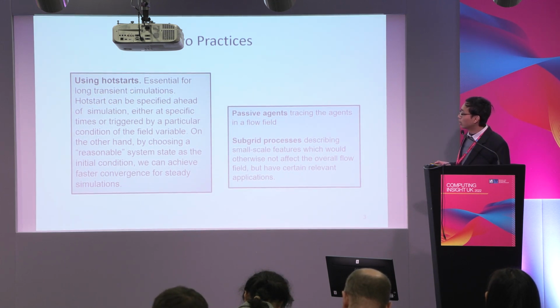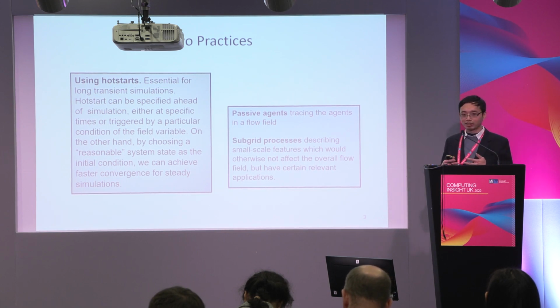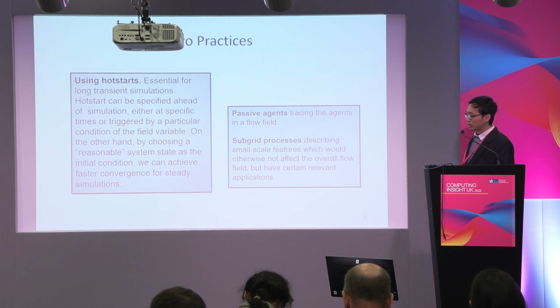It's also for using hot starts. For example, we have carried out long simulations, and maybe we simulate just half of it, see the result, and save it for restarting the later half. That should be okay. A hot start can be triggered by time or by a particular condition.